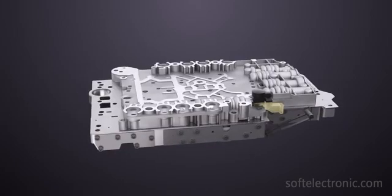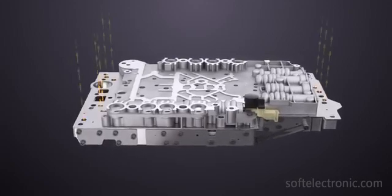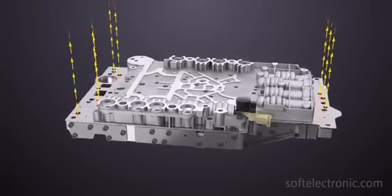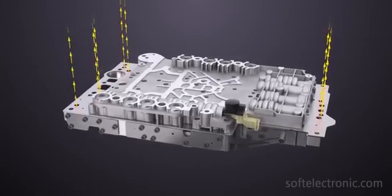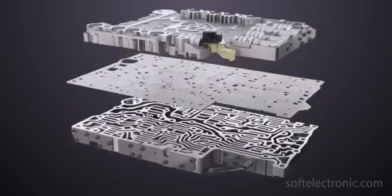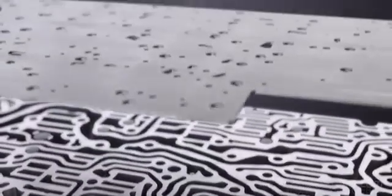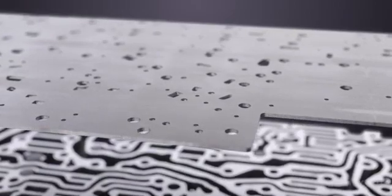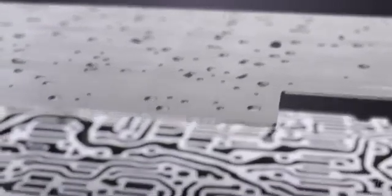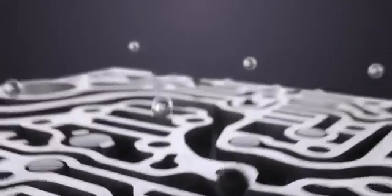The valve body is responsible for the hydraulic control in the automatic transmission. Its role is to manage the fluid flow to the various sections of the gearbox and the torque converter. It consists of the following components: plates with fluid paths and valve seats, gasket with gaps on specific places, hydraulic valves, springs, plastic and metal balls.